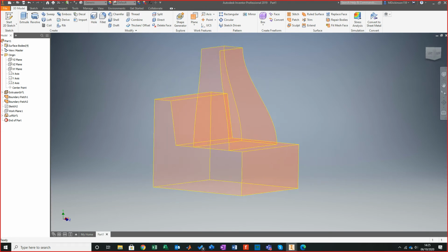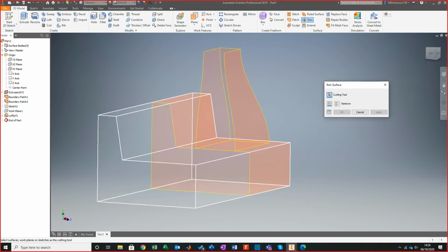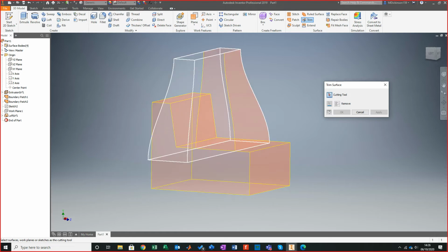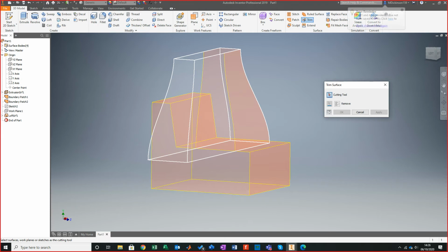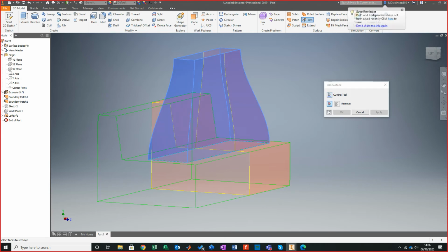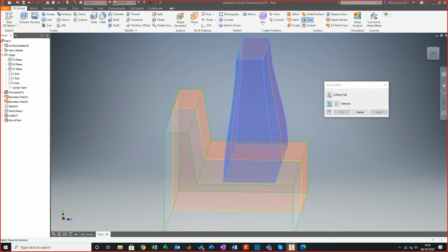Right, now in SolidWorks we either choose a standard, we choose a mutual, and I know we did a bit of it last week, but this is even more blatantly obvious what we're doing. So what I'm going to do is say trim, and then it comes up and says, okay, what is your cutting tool? I can choose that, but where that's interfacing to the base here, I'm going to use this as my cutting tool. Then it says, right, you've chosen that as your cutting tool, what is it that you're going to remove? So I can pick on the outside, and I don't know how well you guys can see it, but you can see there that the outside body is highlighted.